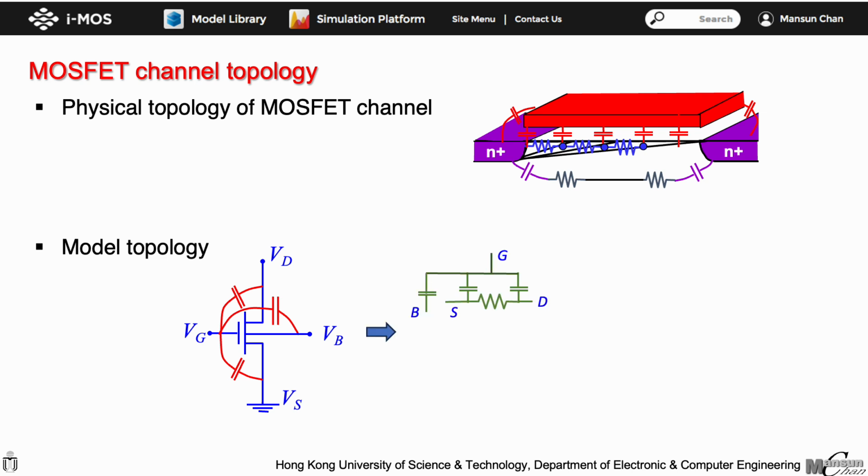In such a representation, there is no resistance for the current paths from the gate to drain and gate to source terminals. Therefore, there is no delay in the response at high frequency from the gate to the source and gate to the drain nodes. As a result, the response will not drop even at high frequency. This example illustrated that the lumped circuit model is not good enough to represent the distributed nature of the channel RC network.